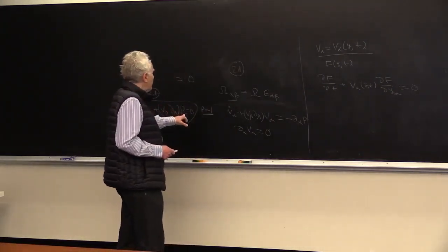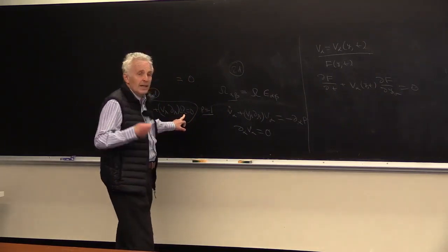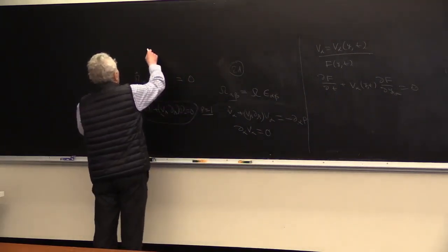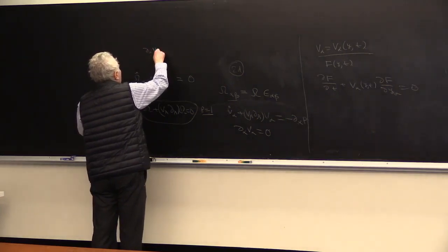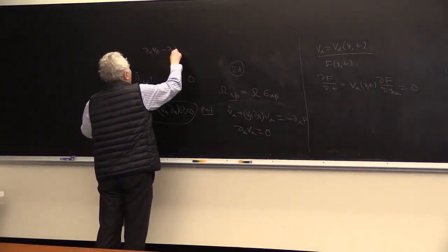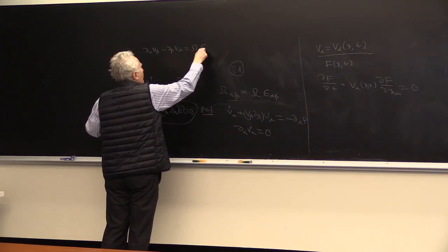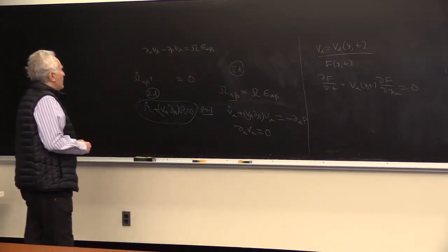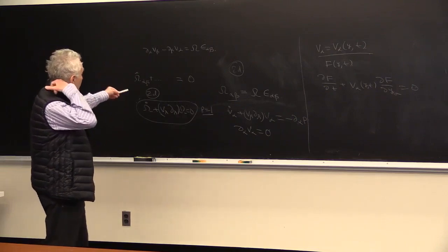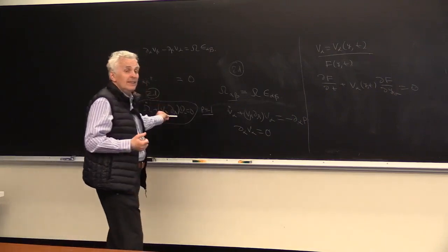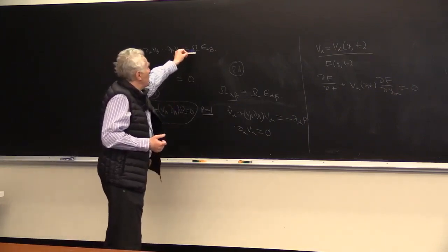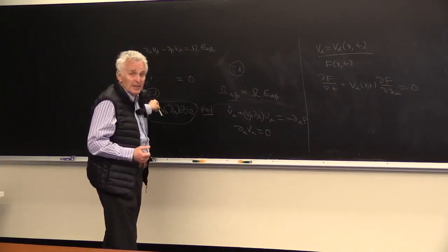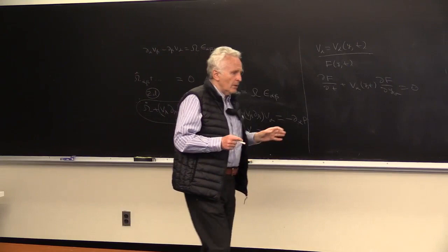Yeah, well, that's really the point. Here vorticity is not an independent function. It is defined by velocity, so this equation is highly nonlinear because you have to substitute omega expressed in terms of the velocity back here.